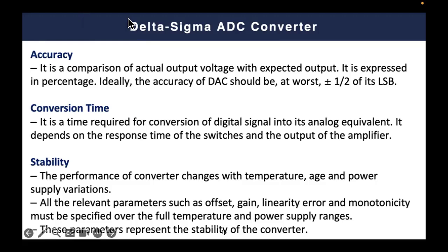Also, what we call the conversion time, which is simply the time needed, or number of clocks, from starting the digital input up to getting the settled steady state analog voltage. So this is what we call the conversion time. And definitely this is very critical for real-time high-speed applications when you have a series of data coming to the DAC that needs to be converted into analog voltage. Of course, settling time is very important for system on a chip and sensor on a chip applications with relatively high data rates. You have to consider the conversion time.